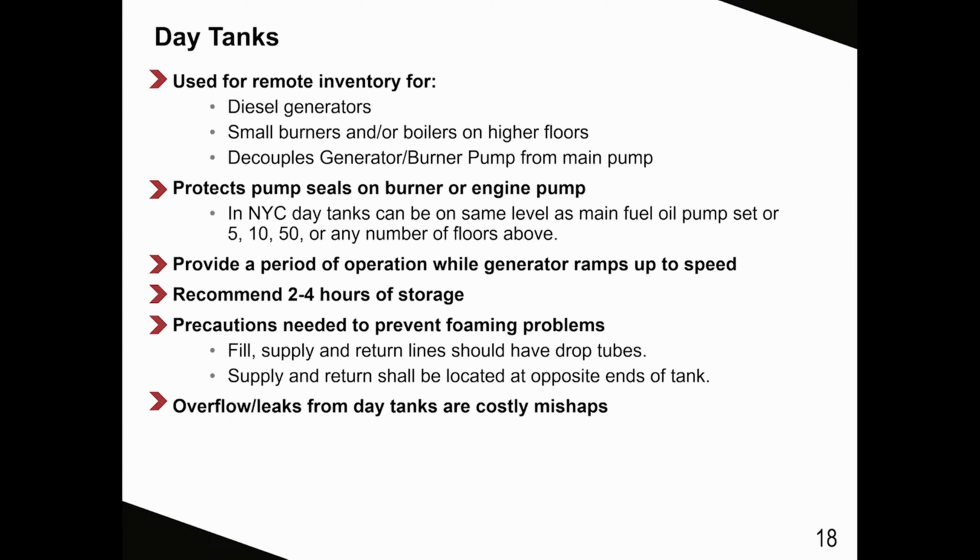We recommend a 2 to 4 hour storage at the remote device. Use drop tubes to prevent foaming problems. The return pipe can be extended at least half the distance to the bottom of the tank. For good circulation, space supply and return piping as far apart as possible, each near the bottom of the tank.